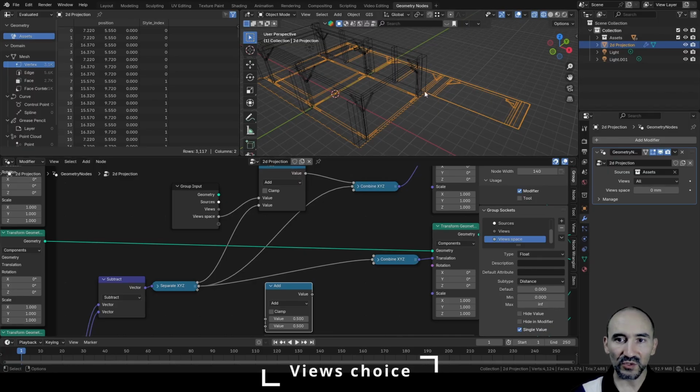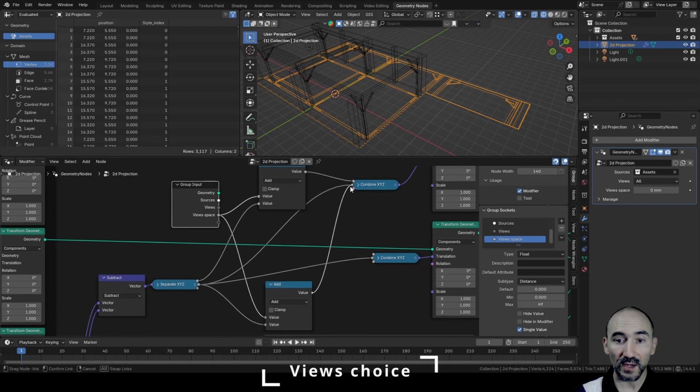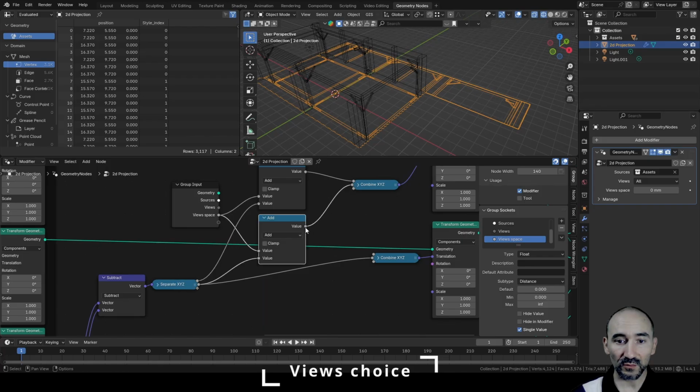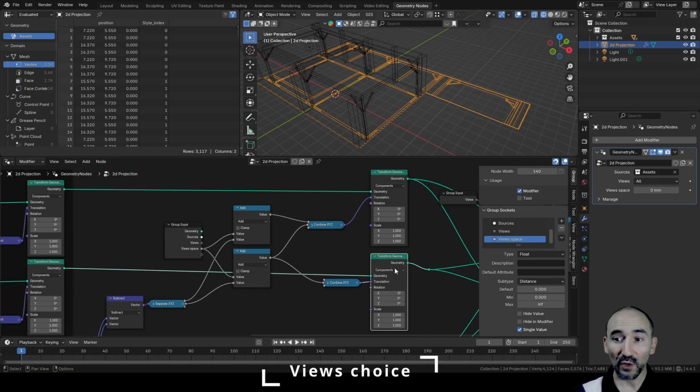So the gap needs to be the same, and we can use this view space here, linking the Y component before going inside the combine X, Y, and Z, and the same result of the Y we can link this in the combine X, Y, Z for the 2D projection of the front view.